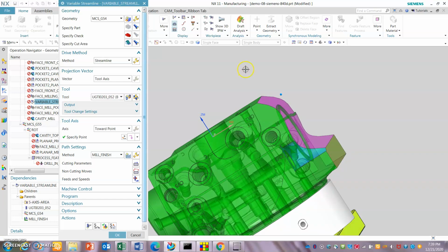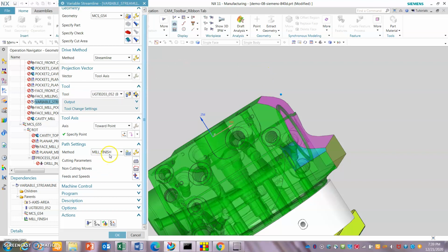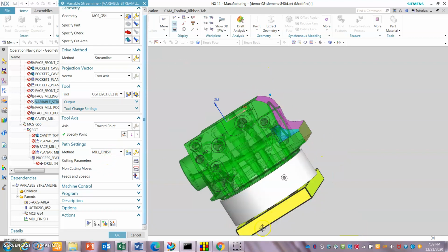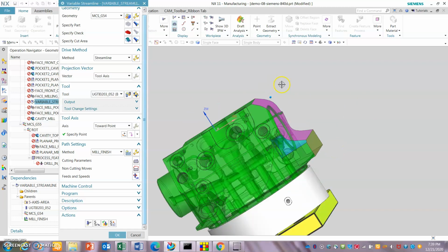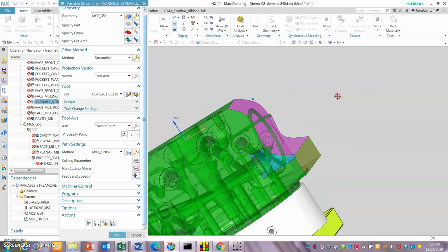You can use that IJK to define G43.5 independent of machine kinematics. With G43.4, you will get A, B, and C depending on your axis order configuration. Therefore you need to define the table based on your table setup, even the table's tilt center line and the Z-axis rotation. If the offset is different, you need to reconfigure the post and everything.